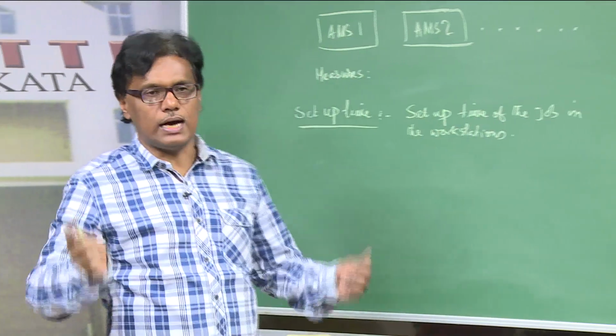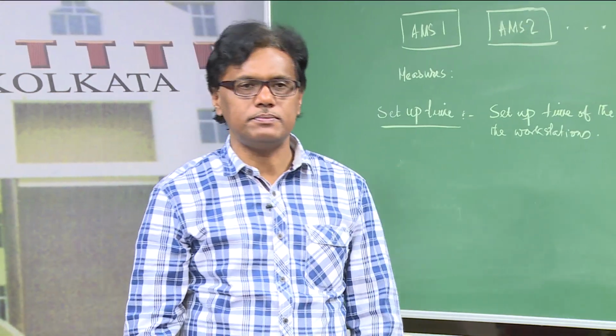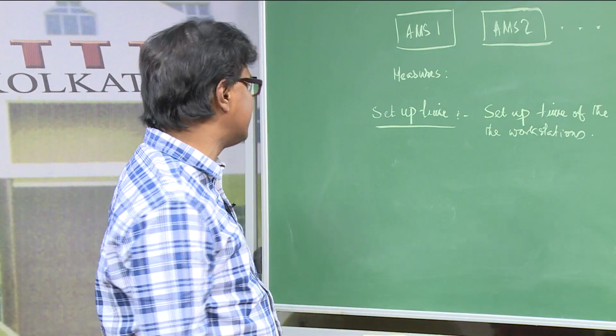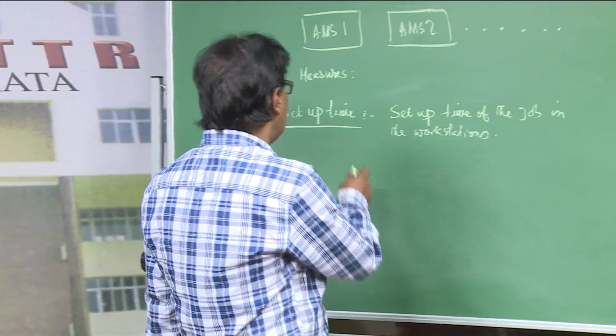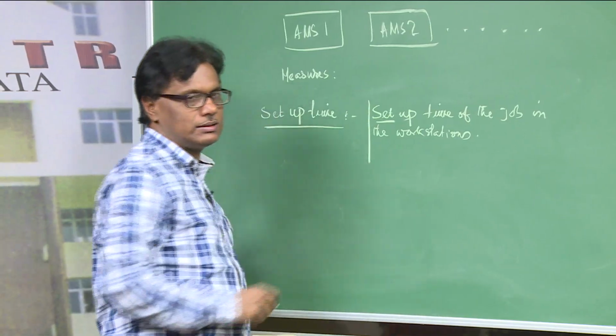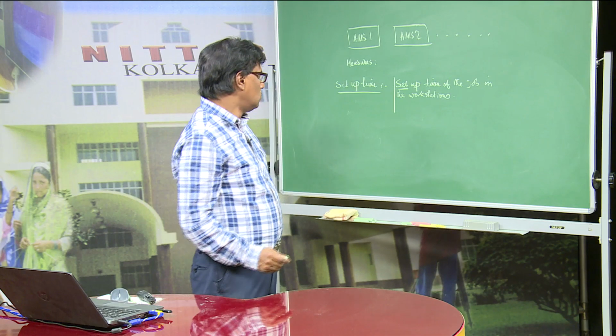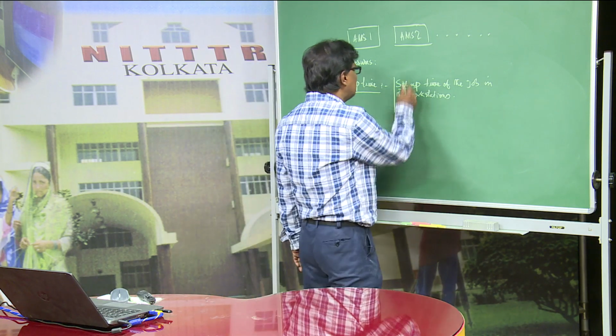It has been observed that at least 15 to 20% of the time is spent on setting the job in the workstations. So, how to reduce this time?